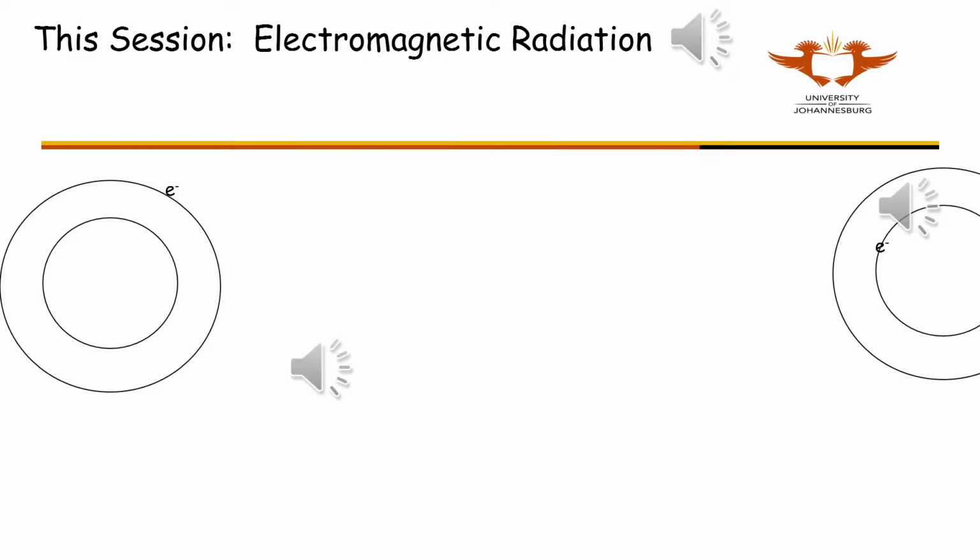Radiation occurs when an excited electron, in a surface molecule or atom, drops to a lower orbital, generating a magnetic field, which, in turn, generates an electric field, and so on. Hence an electromagnetic wave results, and this is propagated through vacuum, or a gas, until it encounters an absorbing surface. At this surface, an electron can be excited into a higher orbital, increasing the energy, and hence the temperature, of the absorbing surface.